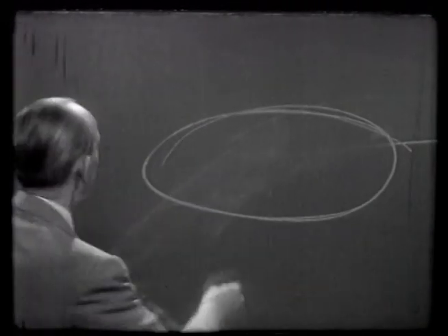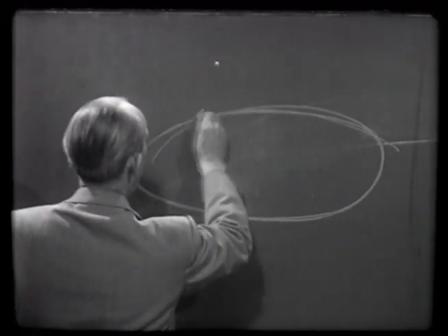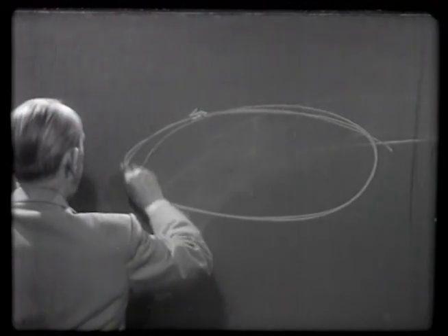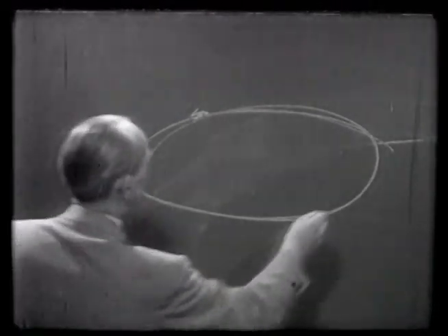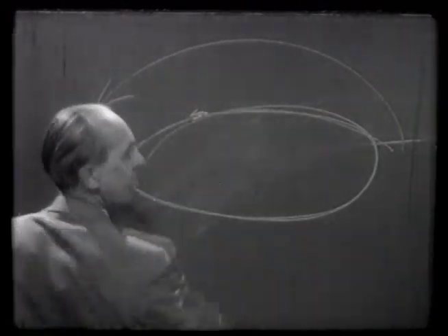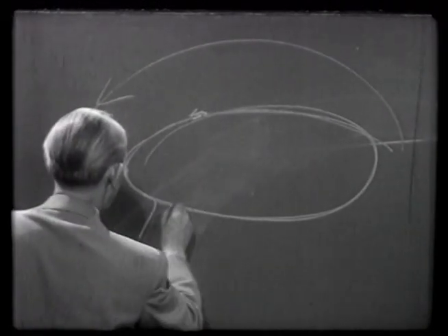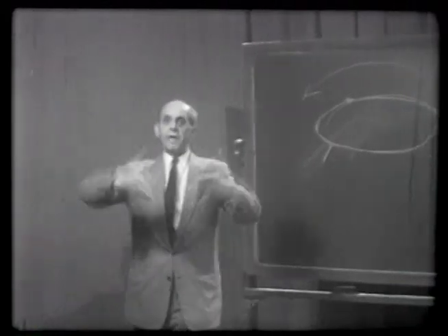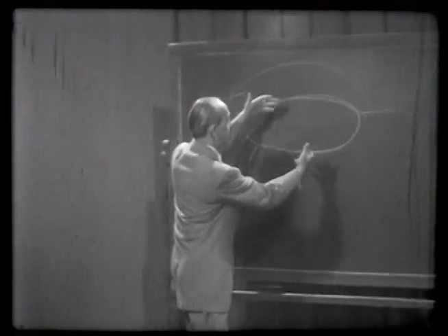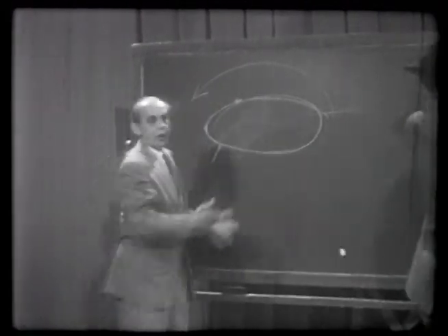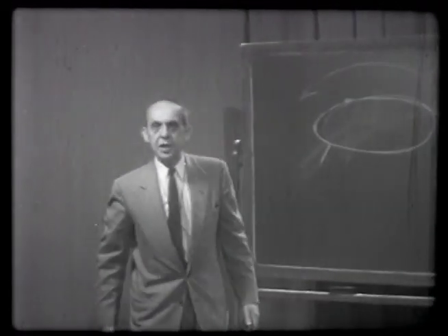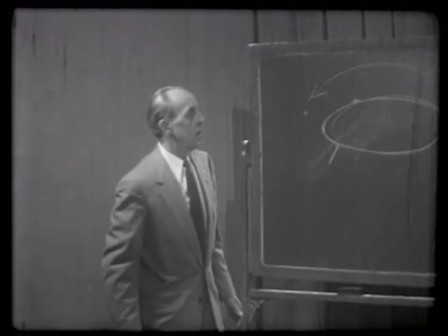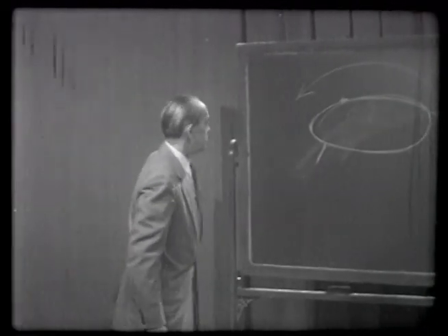What you would do then, you would blow out air over the upper surface and probably at the rear to make the circulation going and achieve in this way a configuration which gives very high lift. And this high lift with a cross-section which is easy to be built and constructed.